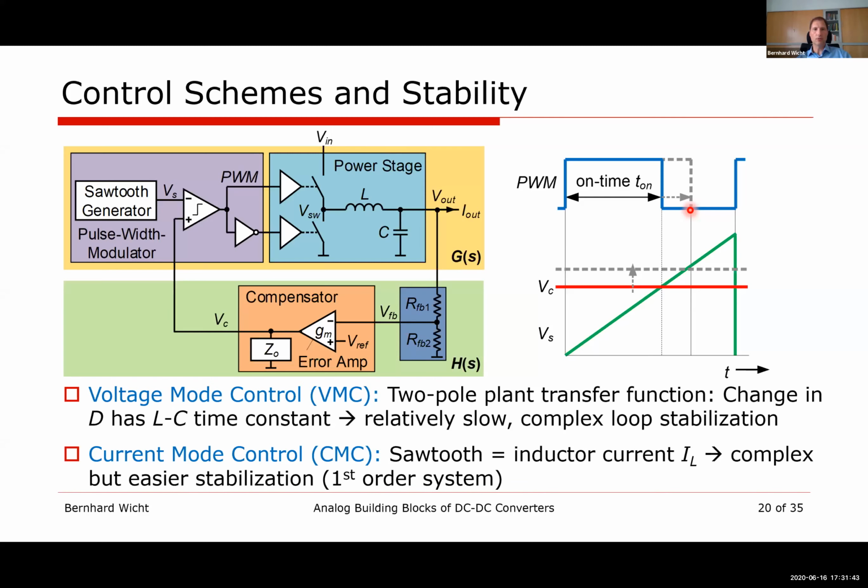In order to address that, there are various ways. You mentioned it, of course, I think there's no way to get away without an EMI filter at the input, unfortunately. Yes. And then there are some additional things we can help with on the design side. The slopes of these drivers could be adaptive.